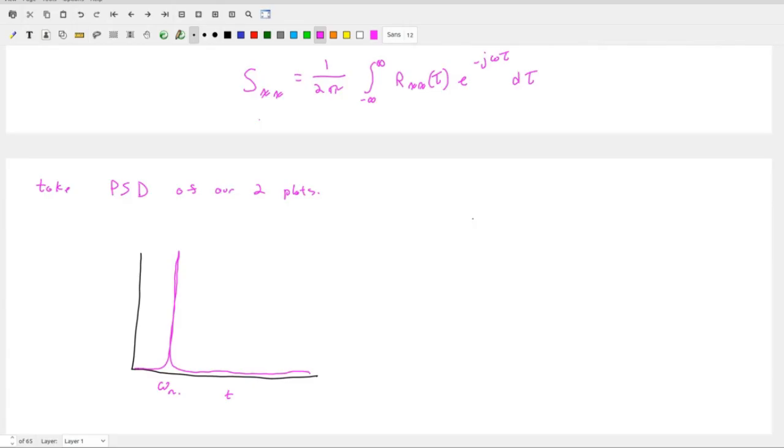Okay, so what are the units for PSD? It's a little confusing, but it depends on what your units coming into the system are, right? So we just look at our power spectrum density, and we don't consider it to be for energy. Let's say we're measuring our accelerometer in terms of voltage. We're going to have signal squared per hertz.